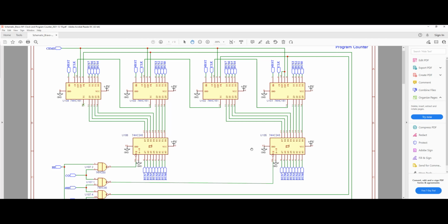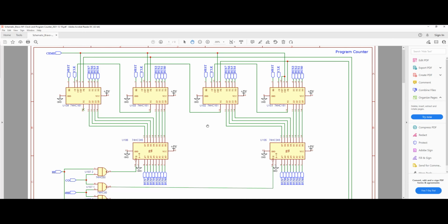For example, your A and B registers would probably also need to be 16 bits, or your ALU should be a 16-bit ALU, and so on. So essentially, you probably need to expand everything in the computer. Otherwise, you always have that concept of high byte and low byte, and you need a sequence of 2 clock cycles to get that information from a 16-bit, let's say, program counter to an 8-bit bus.